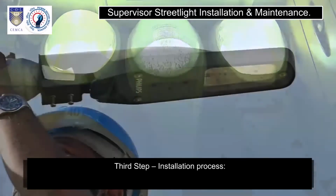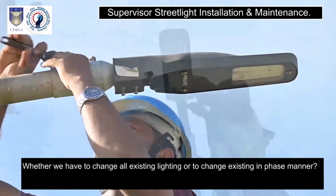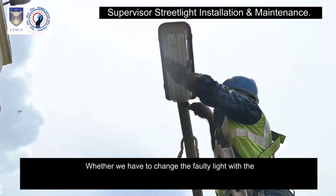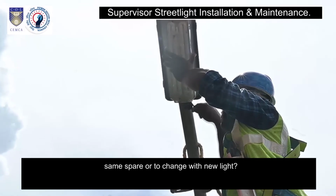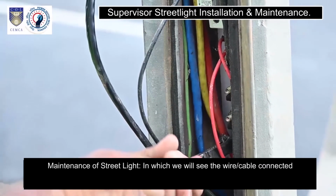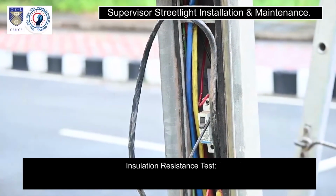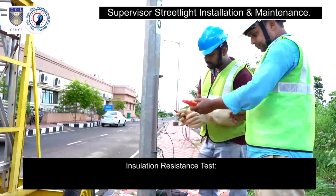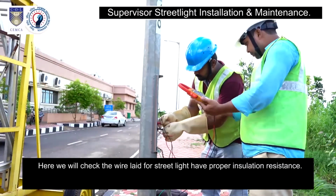Third step: installation process. Whether we have to change all existing lighting or change existing lights in a phased manner. Whether we have to replace the faulty light with the same spare or with a new light. Maintenance of street light, in which we will see that the wire cable is connected properly. Light operation, that is switching on and off. Insulation resistance test. Here we will check that the wire laid for street light has proper insulation resistance.